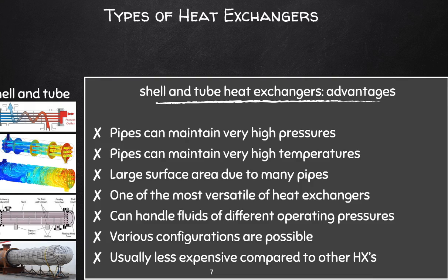And these exchangers can be easily cleaned. Specifically the tube side. The shell side can be a bit tricky. I saw when I was at Sasol how they had opened a shell and tube heat exchanger to clean it, and it can be quite a procedure to clean the shell side. But the tube side, typically you would want to keep your more corrosive fluid, or the fluid that will foul more, on the tube side, because those are easier to clean.